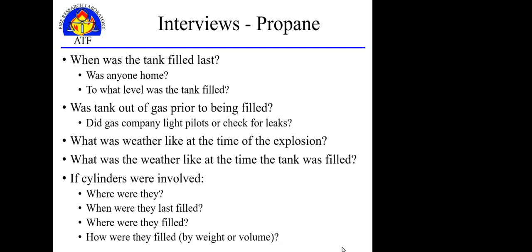Specific to propane, when was the tank last filled? Was anybody home? At what point, or what was the level of the tank that they brought it up to? Was the tank empty prior to being filled? Usually when your tank's empty and it's leaked all the way out, the technician will actually have to do a leak test, and we'll have to check the pilot lights, and oftentimes we'll light the pilots for the homeowner.